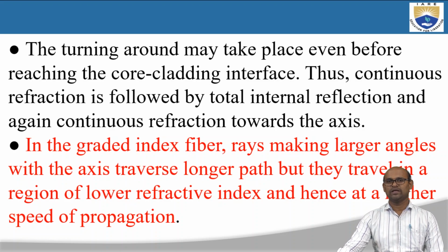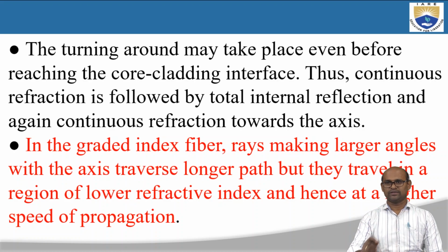So light gathering ability is very small, and it needs costly laser diode to launch the light. Coming to the multi-mode step index fiber, in multi-mode step index fiber, the refractive index of the core is constant. So the rays that are traversing the longer paths are going to reach the output end with some time delay. So the information which you have sent is not going to reach the output end at the same time. There is going to be a time delay.